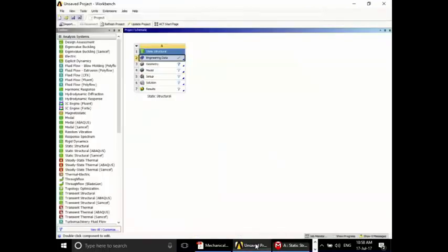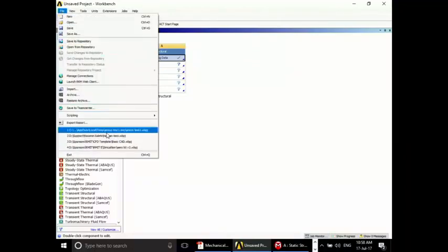Okay, so one of the other things that you may need to do, which I didn't do on here because I don't need to: as soon as you've brought the geometry in, save the project. Don't save it on your network drive because it will not solve, or possibly not solve. I think there's a D-temp, so save your projects there initially. If you want to keep these after this course is completed, once you're finished with the model, you can do a save as.